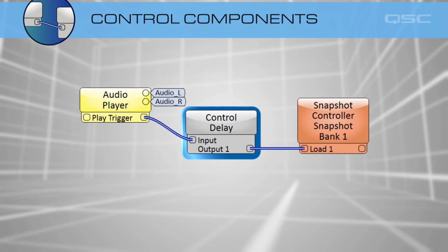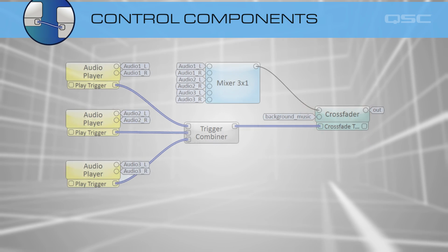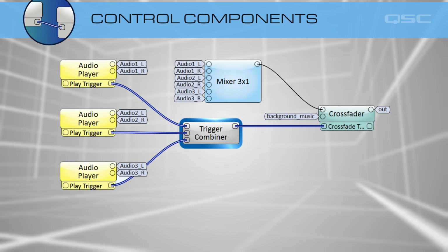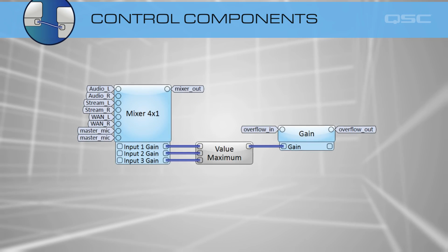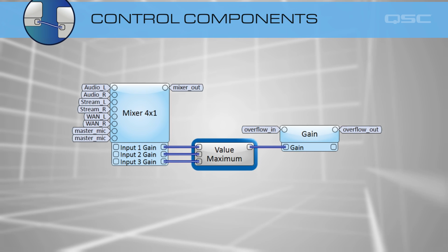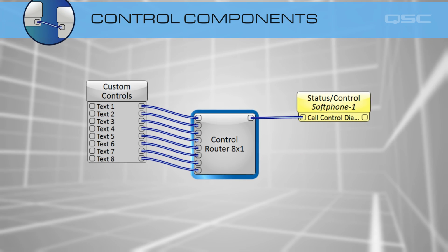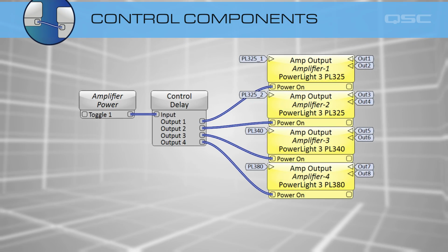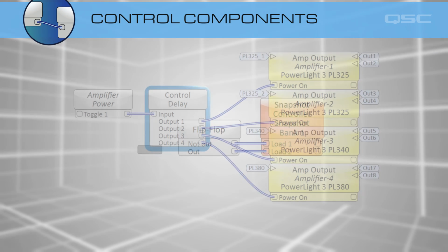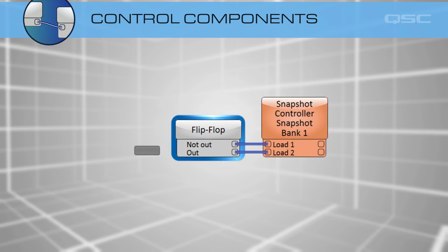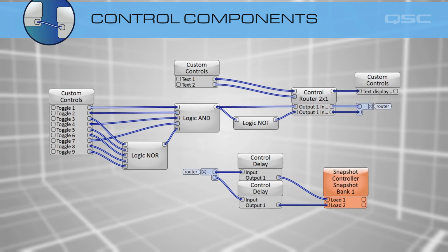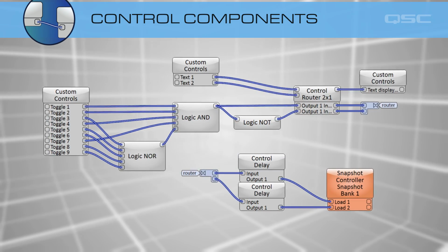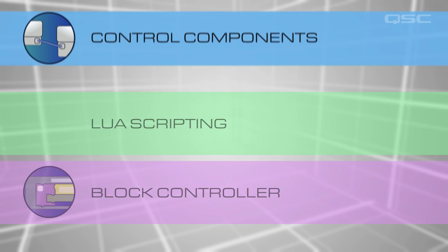Control components allow you to manipulate simple ways for controls within Q-SYS to interact with each other, and apply some basic functions that compare the states of multiple controls, affect different options based on a particular input, and gate logic paths on or off. Control components are great for simple interactions, or for deciding between 2 choices. You can certainly get clever with them to make more complicated scenarios, but eventually you're gonna hit a wall where you need a more robust tool.